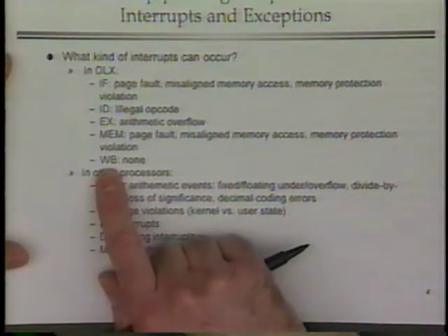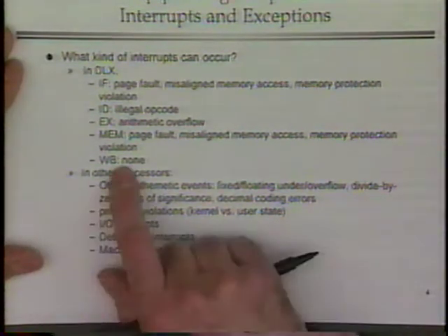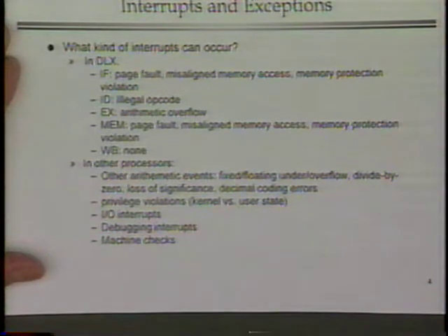All combinations of all 5 write-back bits are possible. Even if you try to write back to register 0, it's not considered a fault. It just doesn't do it. So there's no interrupt or internally generated fault that can occur in write-back.